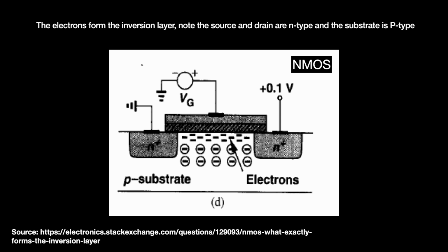As the name implies, the inversion layer is formed from charge carriers of the opposite charge of the well's doped silicon type. Example. So an NMOS moves electrons through its channel, right? When a positive gate voltage is applied to the NMOS, the ensuing electric field attracts negative charged electrons up from the silicon substrate to form the inversion layer, bridging the negative charge source and drain. For this to work, the well must be made from positive type silicon. Otherwise, we do not get proper field effect control over the semiconductor material.